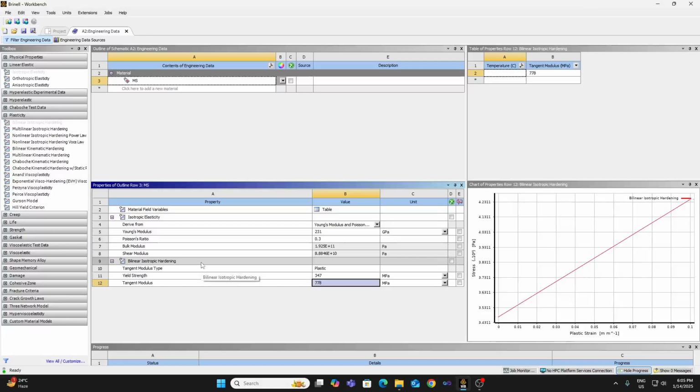So this one is particularly linear, which makes the entire material curve bilinear, as the name suggests. The first part is the linear elastic portion, and this is the plastic portion. So this is the stress versus plastic strain part. So that is also linear. So for that you require only two properties, yield strength and tangent modulus, but different plasticity models will require different types of properties, because in many of the cases this curve need not be linear, and when it is not linear, then multiple inputs to define the nonlinear curve will be required, multiple parameters. But one thing probably would be common is that you also need to insert the yield strength. That means beyond what stress value the material starts having plastic deformation, that also needs to be incorporated.